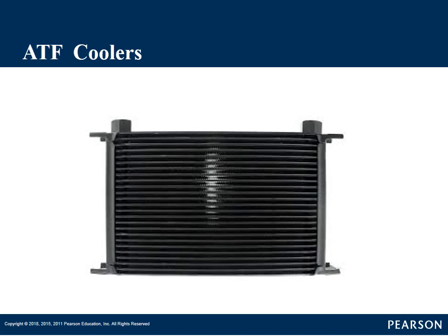Also, the design of these is they don't necessarily run in a tube back and forth. Say if our top row of our stack plate, that top tube gets plugged, it's capable of still flowing through the rest of it. Whereas in a tube and fin, it'd be much harder to plug that, but if it does become plugged, there's no fluid flowing through that tube and fin cooler.